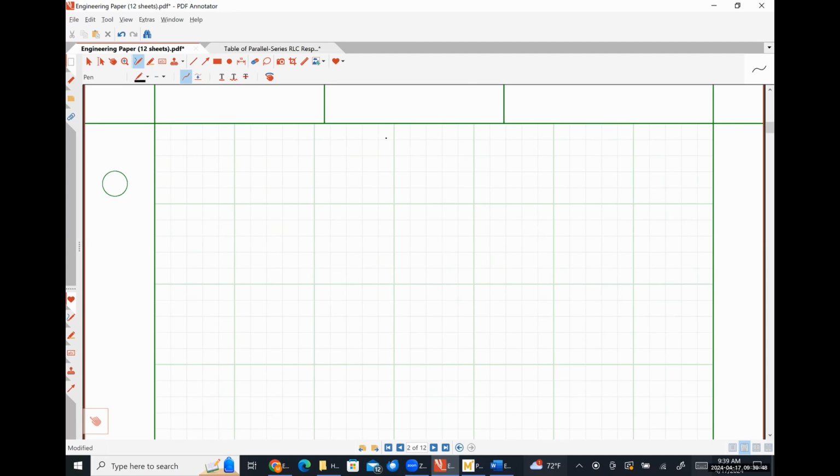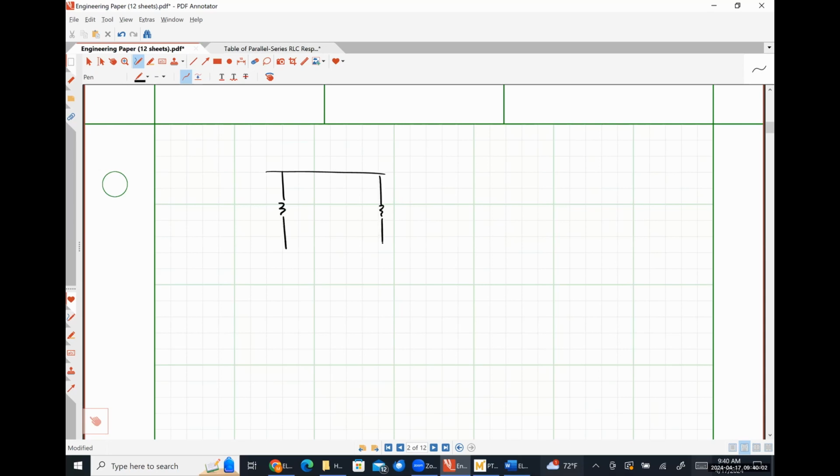For homework 5, particularly calculating your differential mode gains, I'm just going to put these as resistors for now because I don't really care what they actually are. It all looks like a resistor to me. So this is our normal differential pair. I'm going to be lazy and not label a whole lot of things here, right? And when we looked at our small signal analysis, this node X was equal to 0, right?